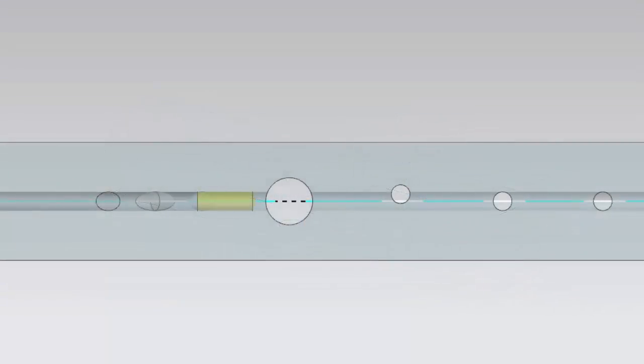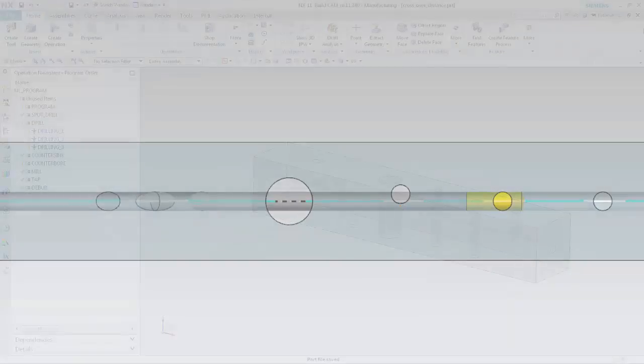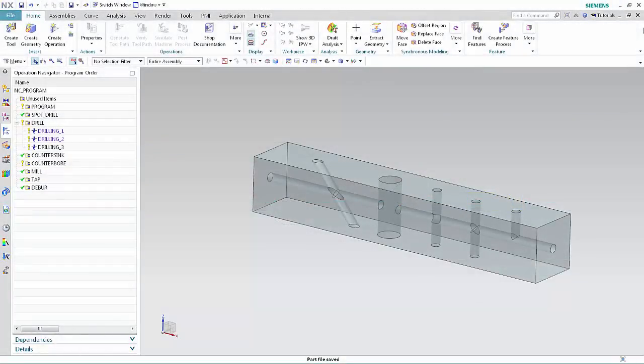Full intersections occur when the shoulder of the tool loses contact with the crossing hole. Partial intersections occur when the shoulder of the tool is always in contact with the crossing hole. In this example, the cross holes fully intersect and partially intersect the deep hole. We'll begin by creating a deep hole drilling operation that uses the default crossover distance.